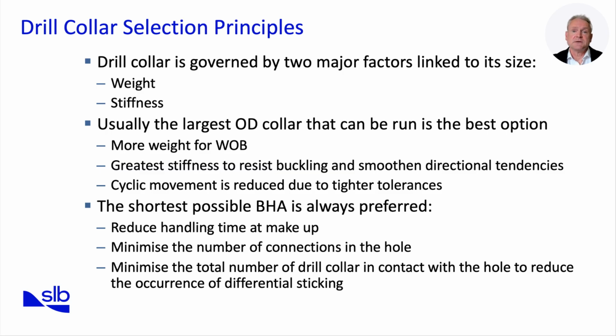Another important design principle is keeping the bottom hole assembly as short as possible. A shorter BHA reduces rig handling time during makeup, which improves operational efficiency. It also reduces the number of connections, lowering the risk of weak points in the drill string.